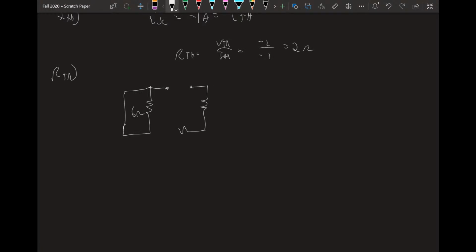And then these resistors stay. A, B. There are no dependent sources, so let's just follow the current flow from A to B and try to find the equivalent resistance. Current goes in here. It can't go here because it's an open, so it has to go down here. If it goes here, it has no way to loop around, so it can't go here. So then it has to complete the loop over here, meaning the only resistance to the terminal C is this 2 ohms over here.